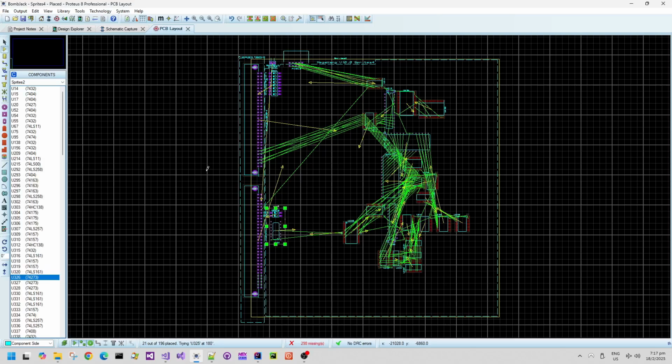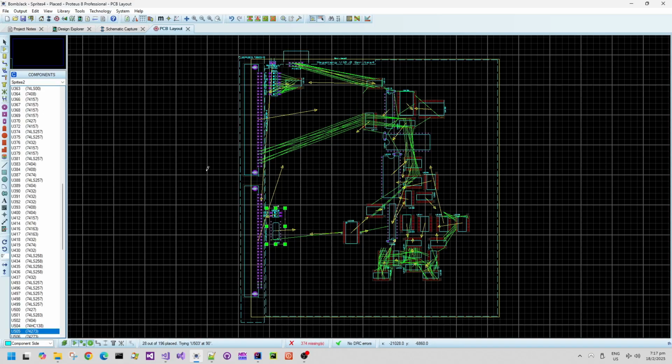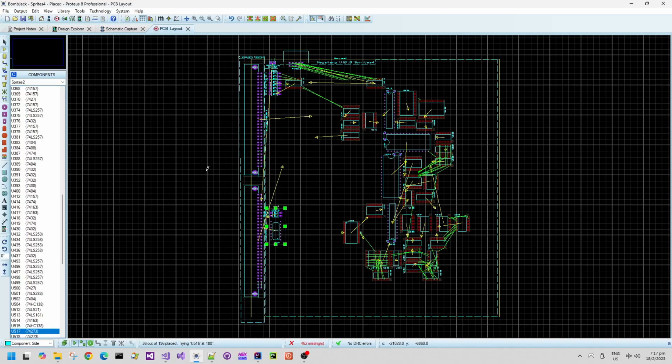I'm not going to do that because I want to test my new hardware designs quickly. Now, because this only runs at something like 12, 14, maybe 16 megahertz, I don't need to worry too much about signal issues that you would tend to get with higher speed electronics. So generally all of my boards work fine with autoplace and auto route.